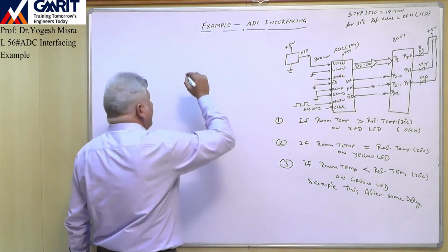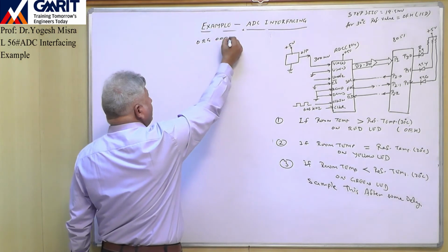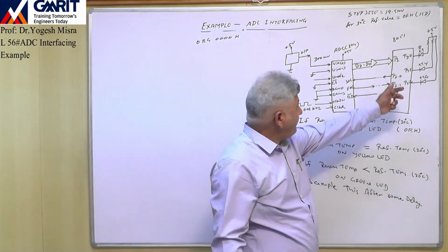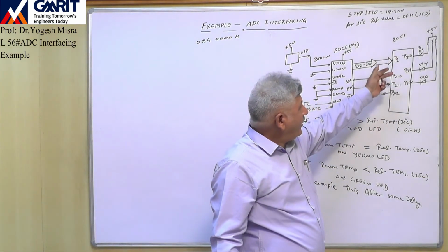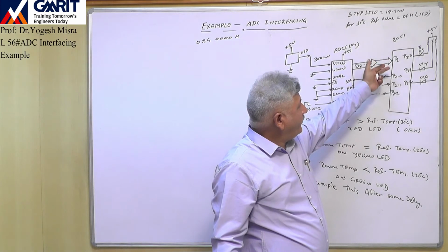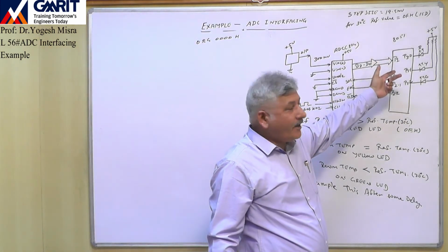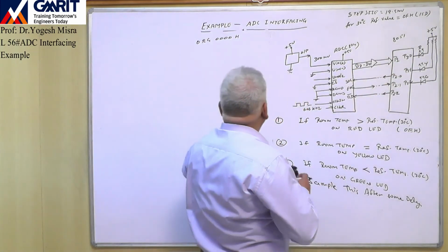So we will write our program from org 0000H. So first thing what you do, you see in this 8051 microcontroller, if there are any pins which we are using as an input pin, then make these pins as input. So here port 1 is acting as an input port. So make this as an input port.